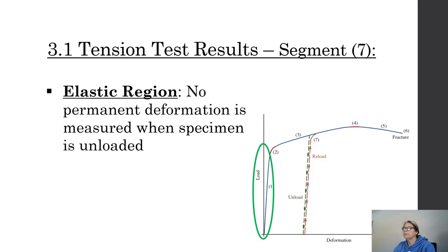Okay, so important things you all have to understand. When we have our stress equations and we look at the stress-strain relationship, the equations are very dependent on our being in the elastic region, okay? If I apply 10 pounds to whatever my cross-section is of my rubber band and then I unload it, it is going to go back. It is going to follow that elastic slope of the line. I can load it, unload it, load it, unload it. There's no residual strain upon unloading. That final length, after I unload it, goes back to the original length.